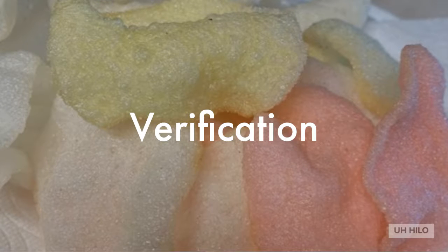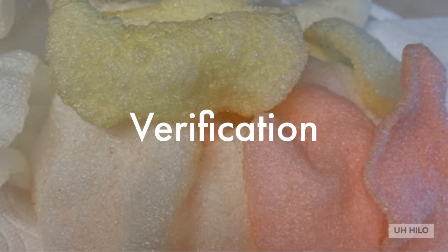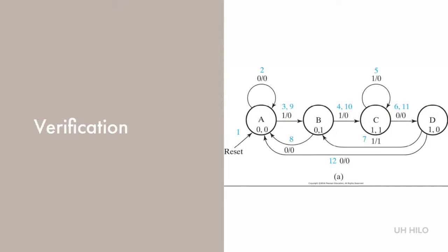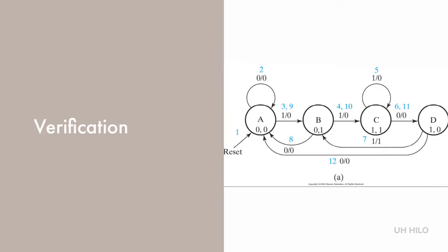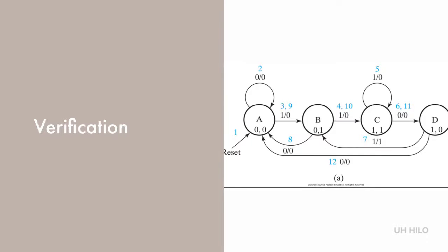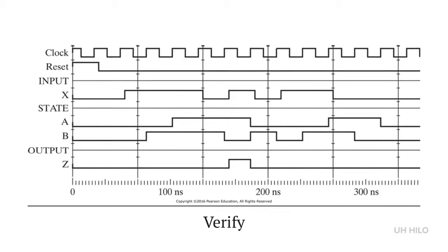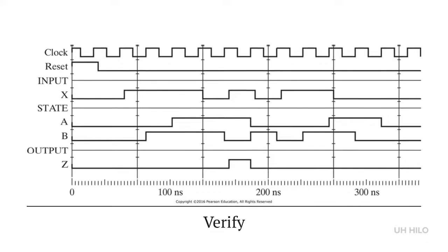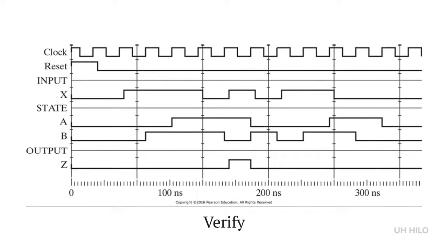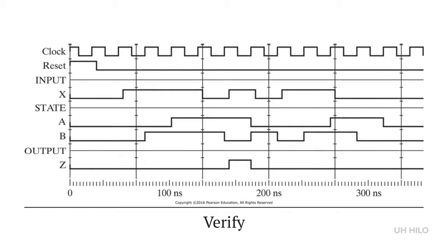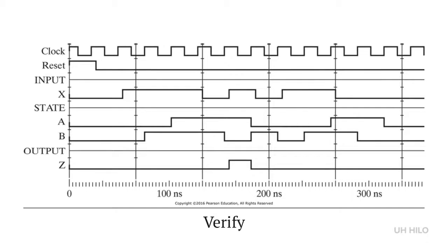In manual simulation, it's straightforward to apply each of the state input combinations and verify the output and next state are correct. For verification by simulation, we generate an input sequence that applies all state input combination pairs. This is accompanied by the output sequence and state sequence for checking the output and next state values. Optimization requires that the number of clock periods used exceed the number of state input combination pairs by as few periods as possible. This can be interpreted as drawing the shortest path through the state diagram that passes through each state input combination pair at least once.